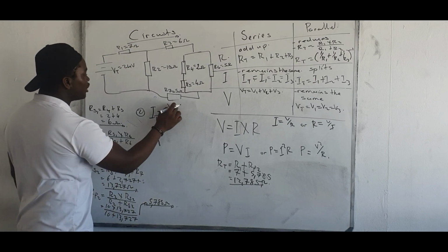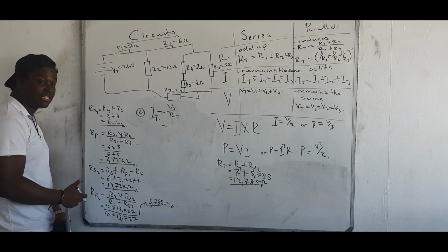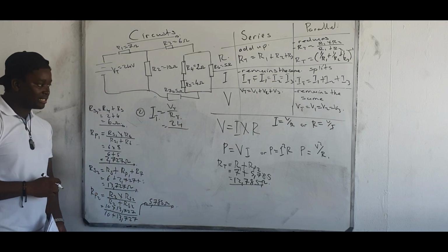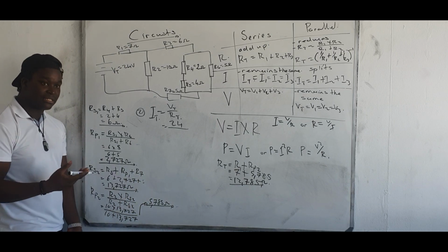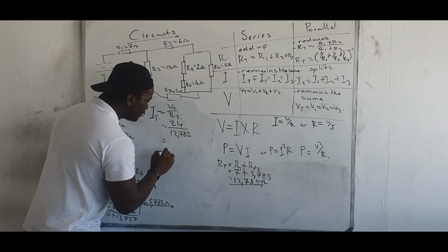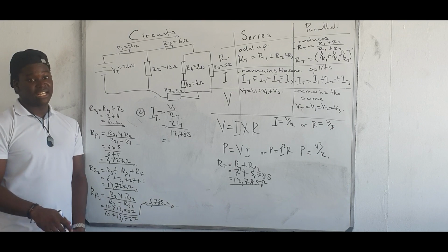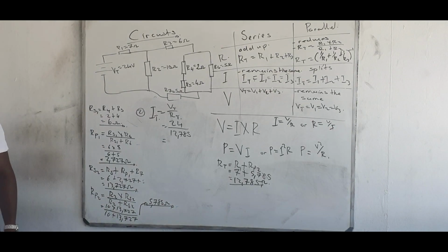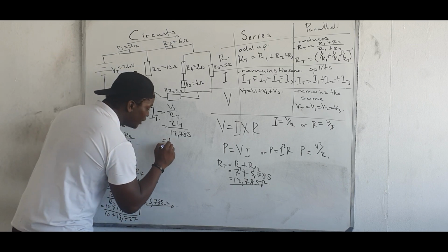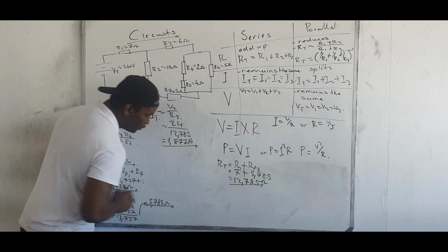Now, what is the total voltage given in this case? The voltage that is powering the whole circuit is 24. That is correct. Divided by the total resistance, which we got as 785 ohms, right? Then you do the division. Your answer is 1.877 amperes. Are we together?